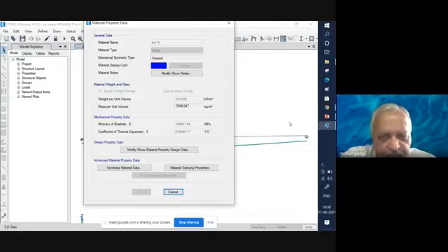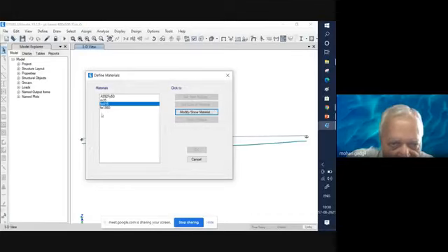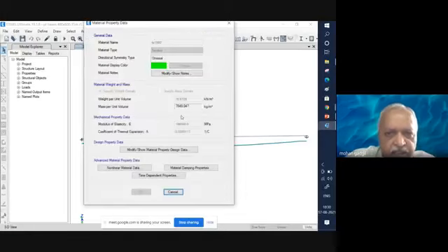Maybe 70% or 80% of the moment might be resisted by prestressed concrete, but the remaining moment will have to be taken by non-PT steel. So for that purpose, I need the data for this non-PT steel, M35, and this high strength tendon that I am considering, the Fe 1860 grade high tension wire. The material properties are like that.